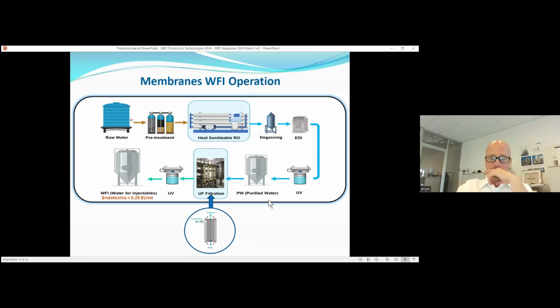There is the possibility of a PW purified water tank or a break tank, then the ultrafiltration module. If it is necessary, another UV lamp and water for injection. So as you have seen, but for the ultrafiltration at the end, it is a PW system at the top of its design.